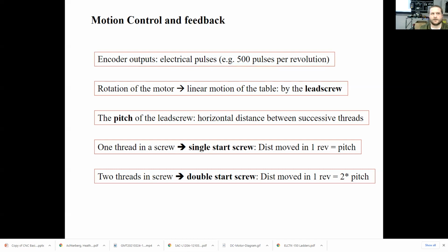I guess it depends on the application, because a robot has all sorts of cables and hoses, like pneumatic hoses and stuff inside of them, right? So you don't want to keep rotating, and you can input faults into the teach pendant that will disallow it, stop that from happening.